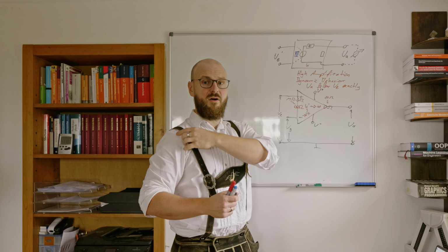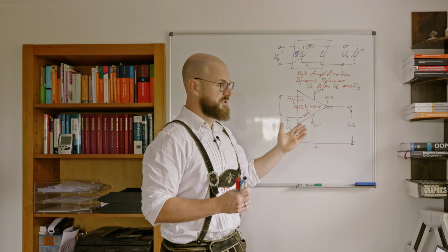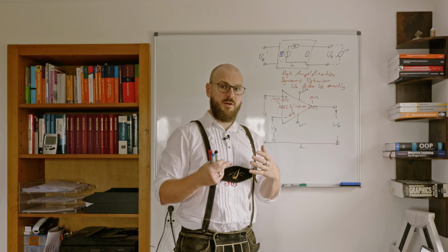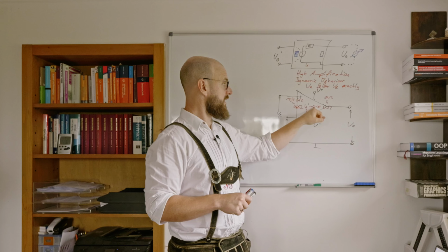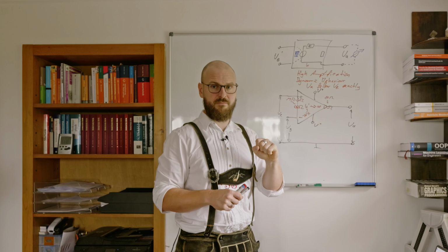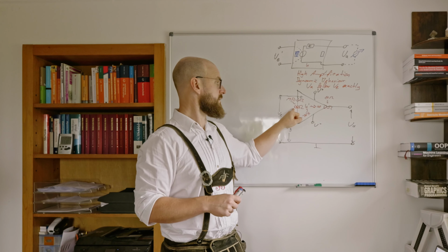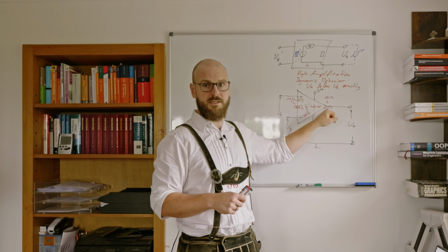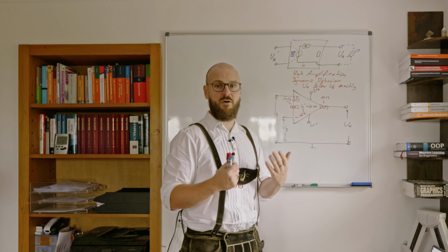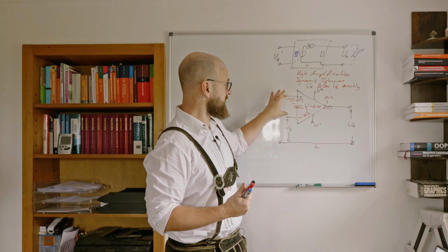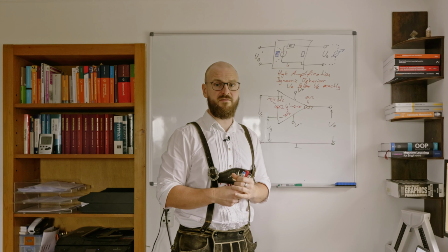And now for all further discussions about operational amplifiers, we will assume to deal only with ideal operational amplifiers, meaning we have nearly infinite amplification, nearly infinite input resistance, no output resistance, and the behavior is perfect dynamically and concerning the offset, meaning when there's no difference at the input, no current will be given at the output.